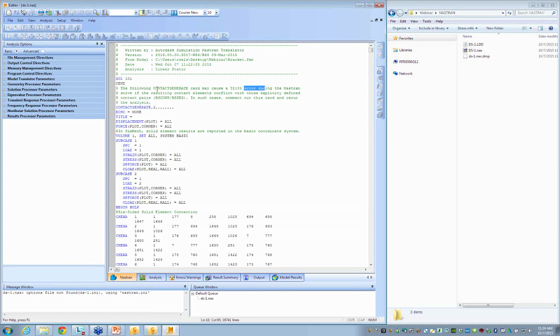And we have a little comment here that talks about this. So if I run it now, it will give me an error message. So if you have a single part, I recommend just putting a $ sign, which converts a text line item into a comment line item, kind of like every other green item that you see here. And now you can run it without any error messages.